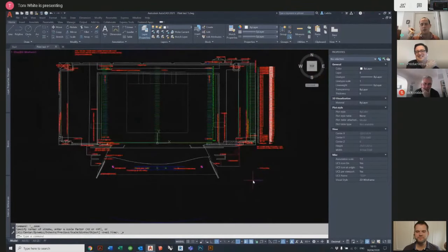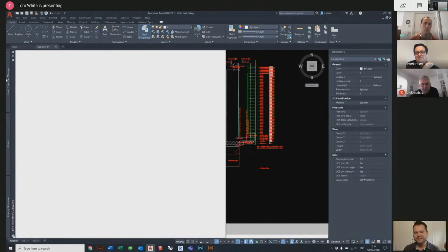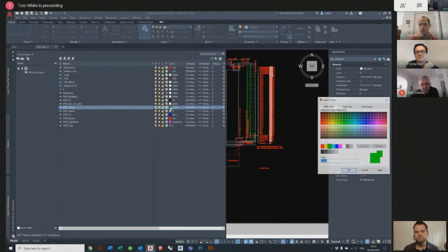I agree with yellow as an issue, but often if you were being sent a drawing that had yellow in the model space, it's more than likely because there's something called a plot style that should have been sent with your drawing, and the quick override is just changing the yellow to any other color. But there's something called a plot override, and it produces that company's desired line color and line weight for a specific color. So if you see yellow, that probably is the reason for it. But yes, you can quickly go to the layer property manager and just click on the color and change it from green to blue or yellow to something else.